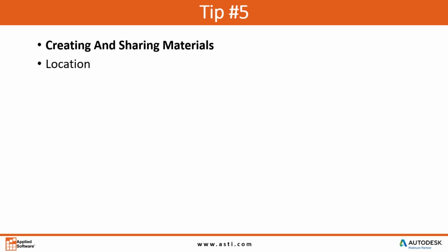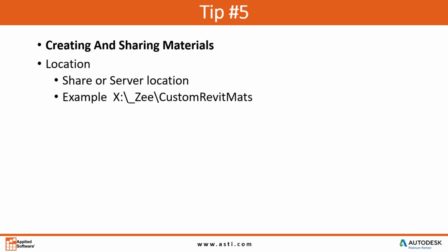So location is really going to be, where do you want it? If I'm creating a custom material, I want to put it somewhere that other folks on my project are going to be able to access it. So it needs to be in a shared location or in a server location. For example, it's on the X drive, custom material, whatever. It could be just within the project itself, or maybe it's a company standard material location.